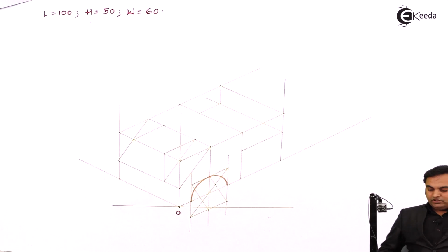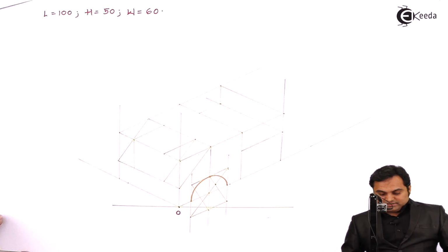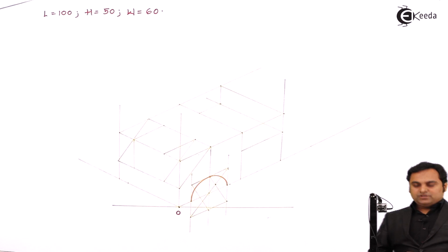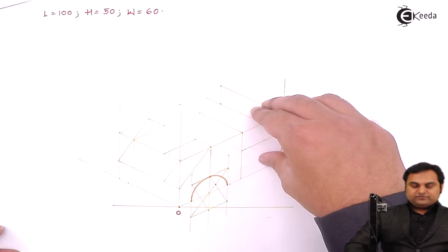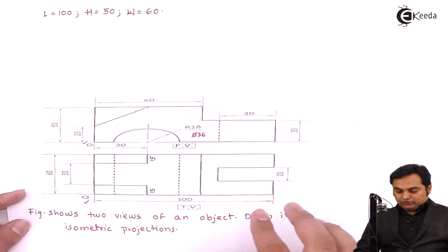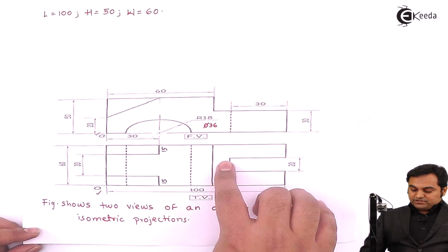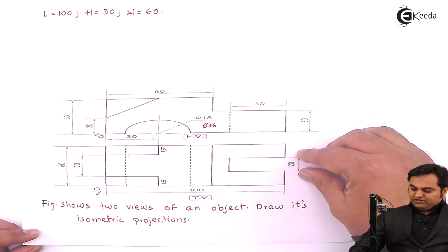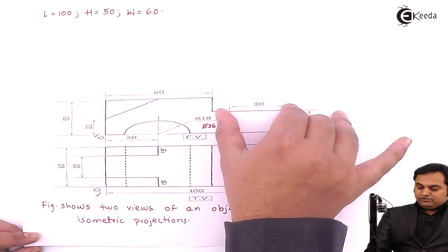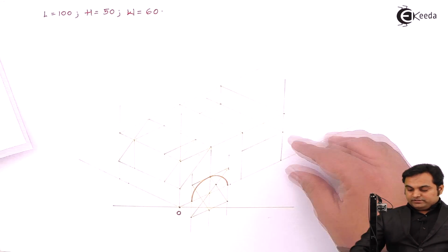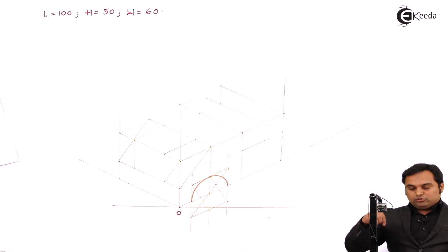So now after completing these surfaces, I leave them as it is, that is I would be making them dark at a later stage. First I'll move on to this surface, that is onto the other side of the block. Now over this side, that is of 40 mm length, here there is a groove. This groove is exactly at the center, having width 20, and the length of the groove is 30 mm, and it is up to a total height of 30. That is, inside this total height, that groove is deep.